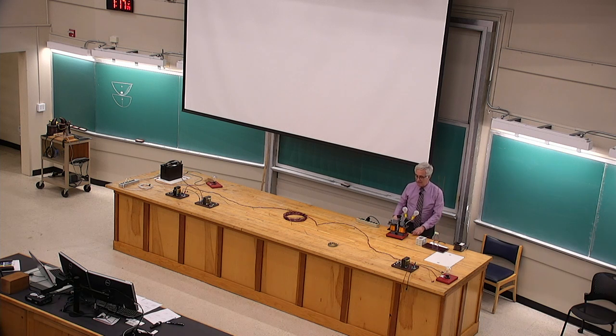So that's the plan. I want to make sure it's clear that we're going to go from one electric circuit, which is the circuit that involves this box and goes in effect to the electric company, to a second circuit which is connected to nothing. Power is going to move from the first circuit, the primary circuit, to the secondary circuit. But no charge will move between them. No magnetic pole will ultimately move between them. Nothing. It's just going in effect through thin air, facilitated by chunks of iron that magnetize nicely. But basically, there's no direct contact between these two circuits.